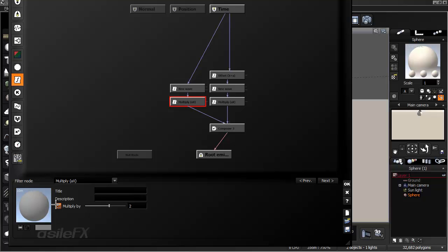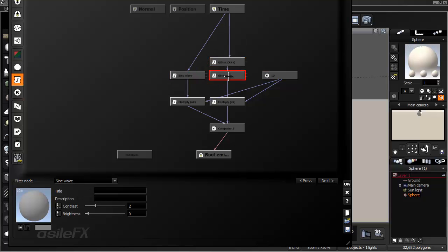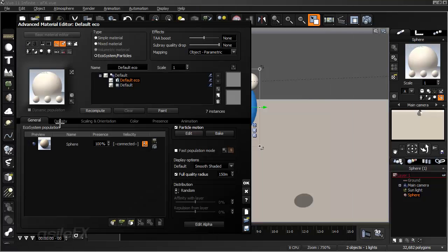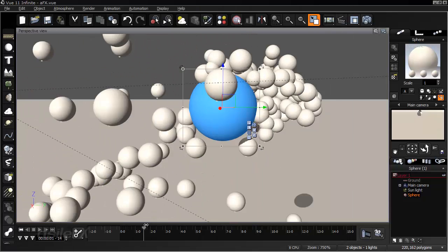What we can also do is go ahead and extract both of these and just use the same number to control and increase both the X and the Y. And you do want to make sure that that's after the sine wave, otherwise it will not be an equal motion on each velocity. And the overall output won't look quite as good for this type of effect.